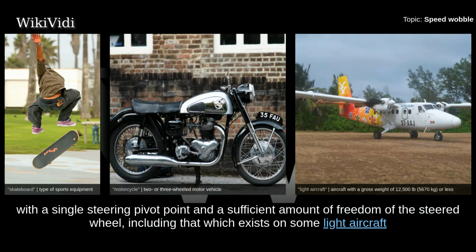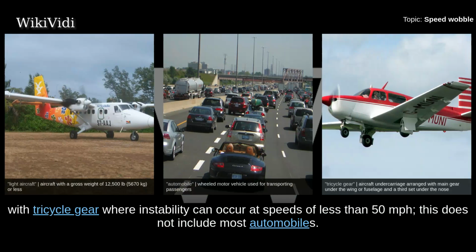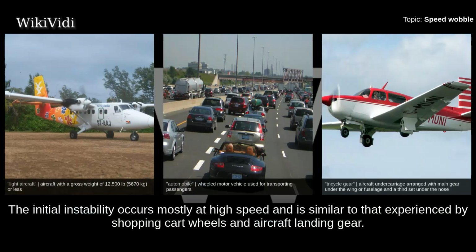Vehicles that can experience this oscillation include motorcycles and bicycles, skateboards, and in theory any vehicle with a single steering pivot point and a sufficient amount of freedom of the steered wheel, including that which exists on some light aircraft with tricycle gear where instability can occur at speeds of less than 50 miles per hour. This does not include most automobiles. The initial instability occurs mostly at high speed and is similar to that experienced by shopping cart wheels and aircraft landing gear.